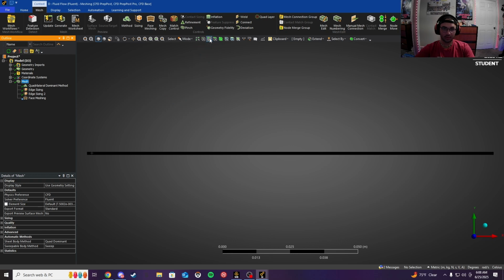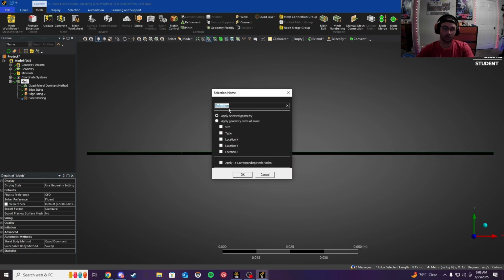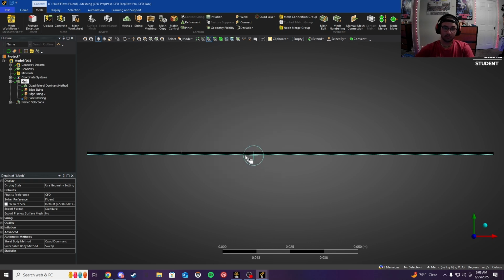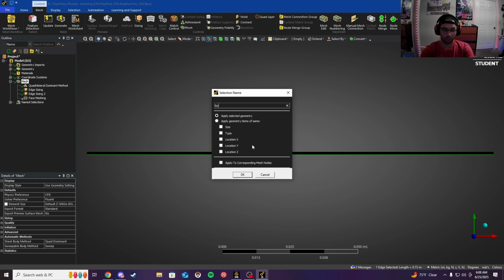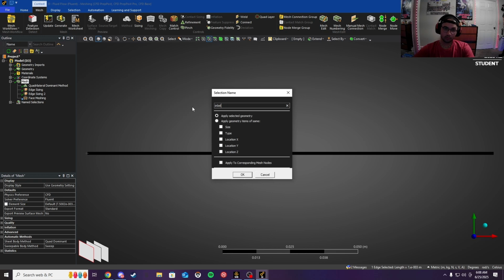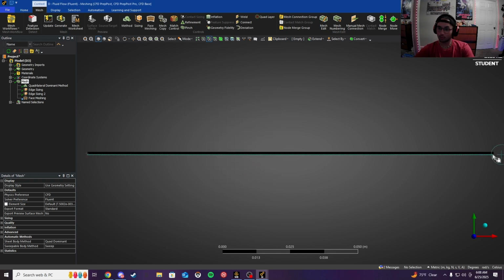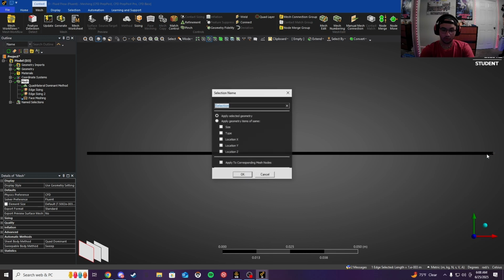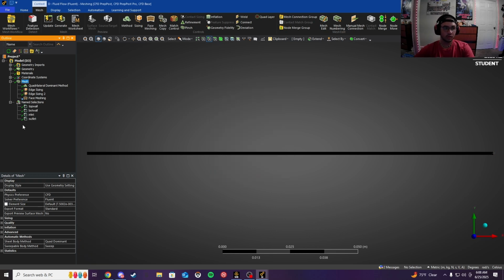But now we can go back to Edge and click on each side now, and once we click on one, press N. Here, you can just change the name of things. Just give them a name. Do that for every single side. The top wall, the bottom wall, and this one you want to call the inlet. That's where our flow will be going, the beginning of it. And the other side we will call the outlet. Perfect. All our named sections.